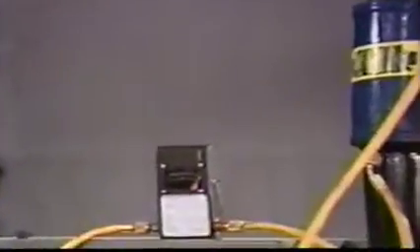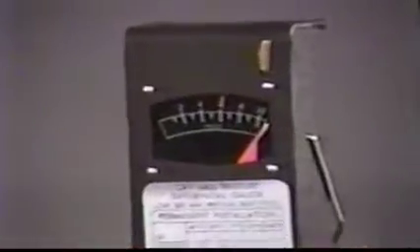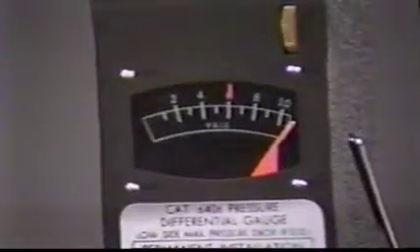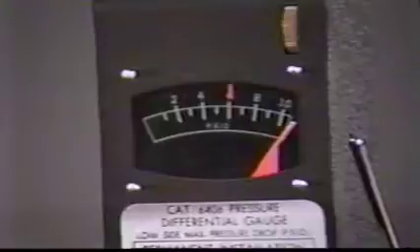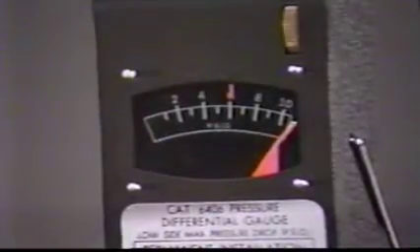Although the suction line dryer will clean up a refrigerant circuit after a burnout, the dryer may lose its value in the process. As the dryer does its job, the contamination picked up will add increased pressure drop to the suction line. If the pressure drop increases beyond acceptable limits, the filter dryer must be removed and a judgment made by the technician on whether to replace it with a new one for additional protection.